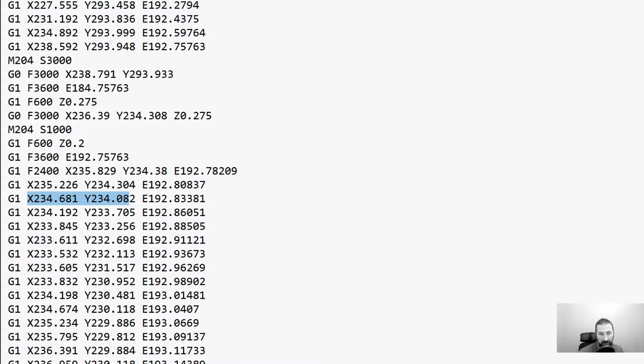And that's it. You just need to write this text in some way to get something printable out of it. You can, of course, design some motion paths with this knowledge which will result in extrusion in mid-air, not sticking to the bed, or going straight up in Z, for example, and the machine will perform this movement, but nothing usable will be printed that way. So you need to find a way to organize these points so you can actually print them in a way that creates some shape and also sticks together. And this is what the slicer does for us.